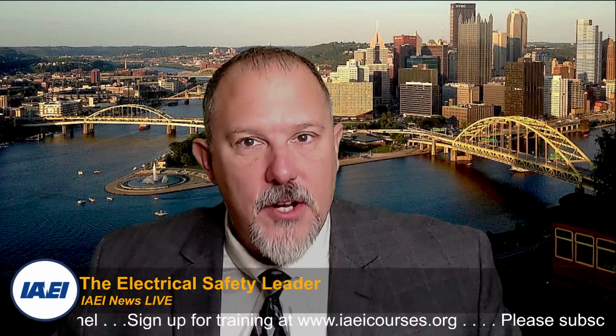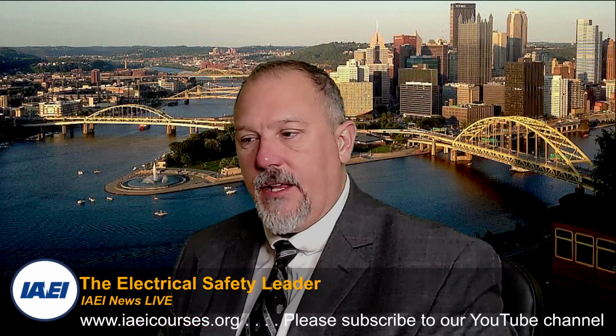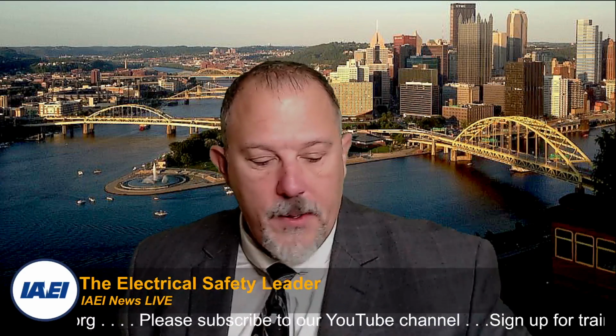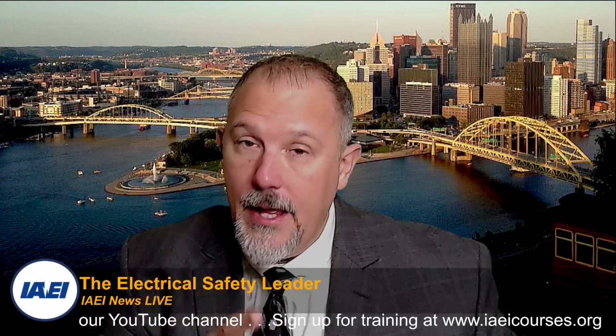The higher the currents, the faster the clearing times. Why would that be important to understand? If I want to understand arc flash, I've heard people say, lower currents give me lower incident energy. That's not necessarily true.